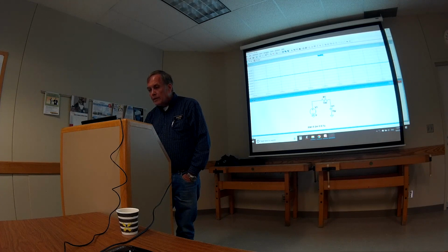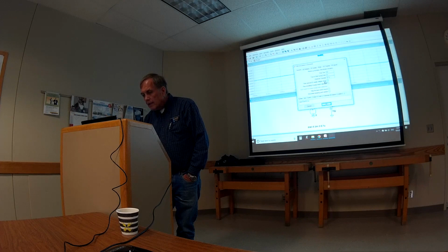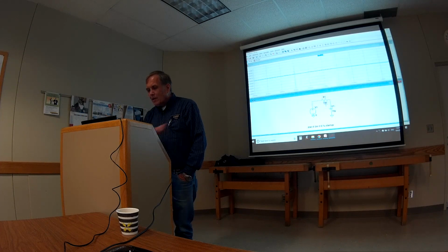Back in the simulate tool, there's a little box down here right in the middle. It says start external DC voltage at 0. That's the one you want to click for this. Otherwise, it's going to go back to the steady state and get up to 5 eventually. So now I'll go back and click the running man again.